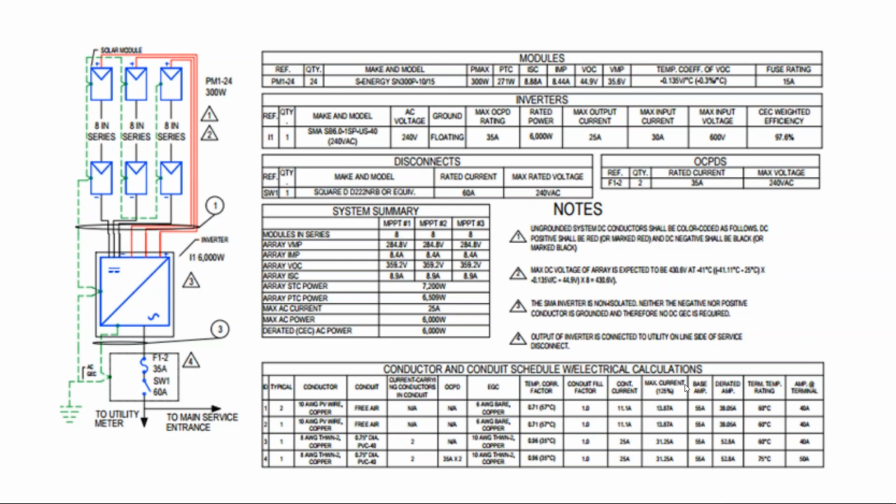So I'll go and do my one-line diagram for my solar array, and then I might switch out the inverter block with my 3-circuit charge controller. Either way, it's still going to be the same voltage and amps coming back to my charge controller, and that's still going to be in the same conduit size.